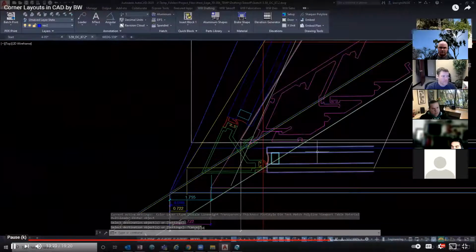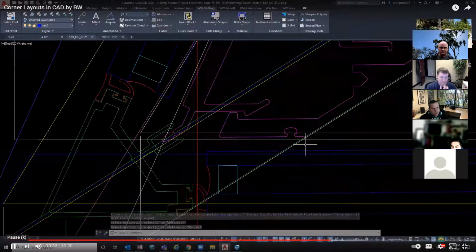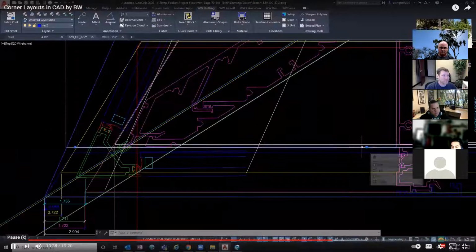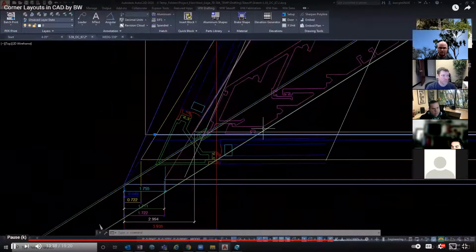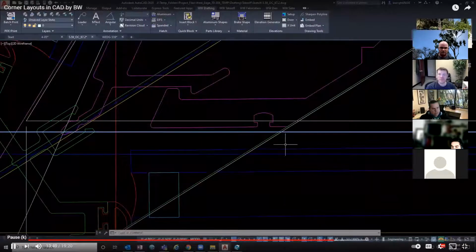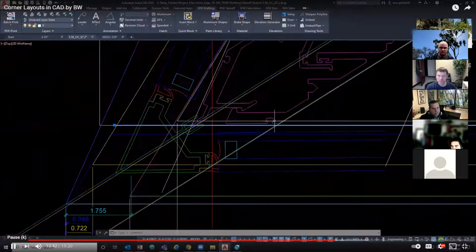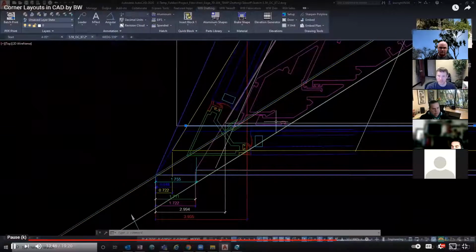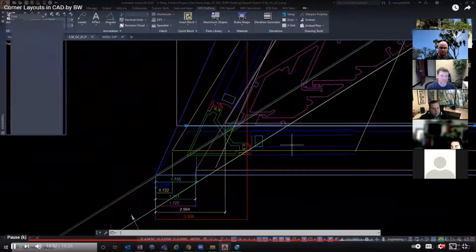I've got all my lines set up now, and this line is my glass pocket line. So my vertical mullions are not fully aligned with the glass pocket. So I want to move those before I continue on the layouts. So I'll use the move command.